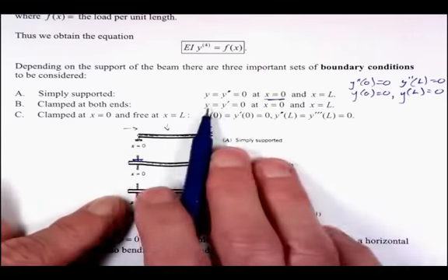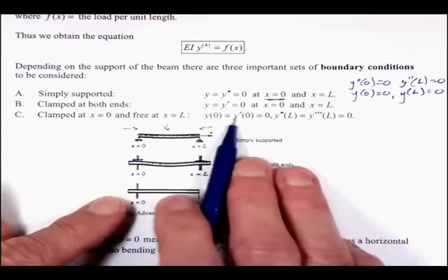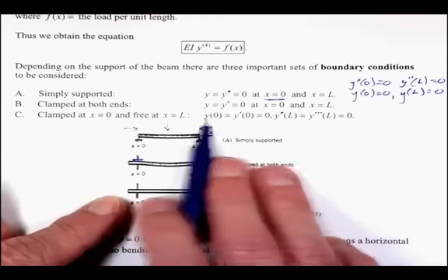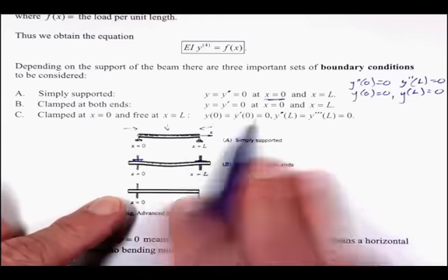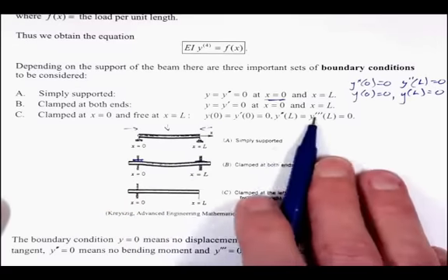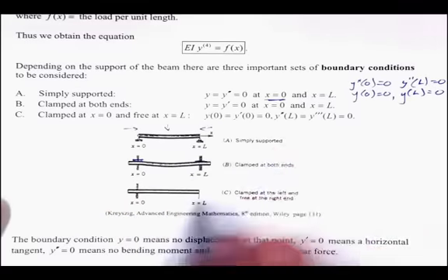So we had y equals 0. So this is saying when x is 0, y is equal to 0, and the derivative is there, so that's the clamping that matches with the previous case. It turns out on the other end, though, that at x equals L, the second derivative is equal to 0. So that's sort of like the simply supported case back up here.